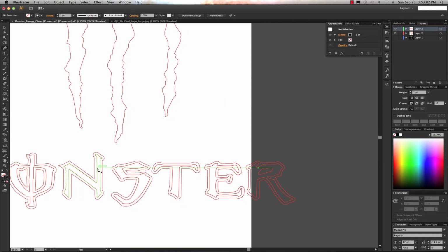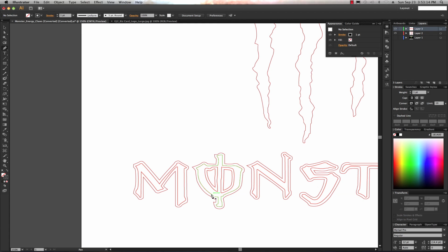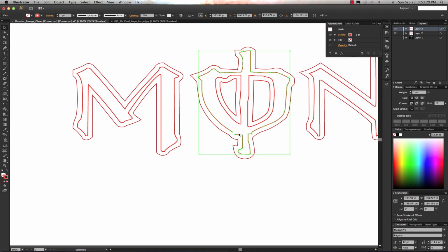I'm going to show you how to use the pen tool real quick, and then we're going to bring this back into Maya and do some beveling and stuff. So right now I can see where I'm going to have trouble. Basically, in our file right here, if I select this curve or this path, you can see right there where it isn't connected. It's not closed. So let's get up on that a little bit more. Right in there, it's not closed. Well, we can close this in Maya, and I didn't do it here, so I just wanted to show you that as we bring this into Maya. Okay? So there it is. We're going to be creating some curves like this in Illustrator and bringing them into Maya.